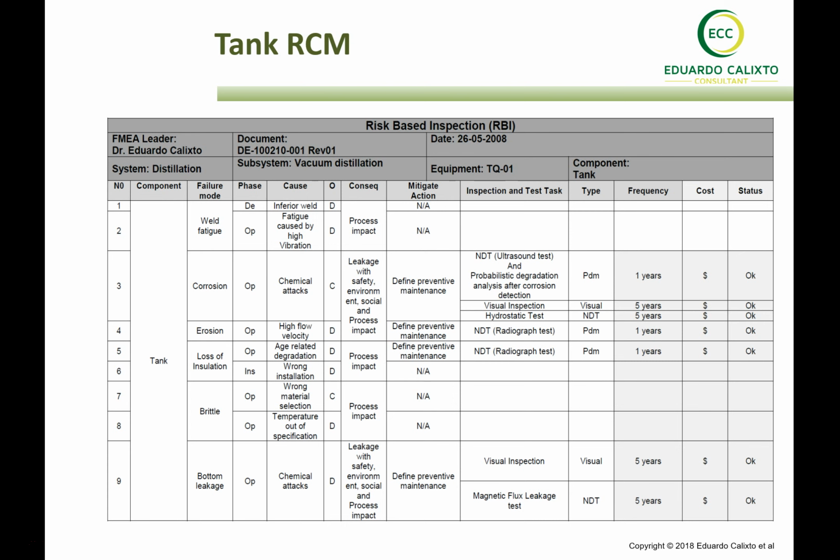So in some cases, it's necessary to put in products whose corrosion level is higher than specified for the tank, and then we can start to have some corrosion earlier than expected. Is that another point that we need to be aware of? In case the corrosion starts to happen earlier because you use products that have a higher corrosion level than specified in the tank design, we need to review the frequency of non-destructive tests.